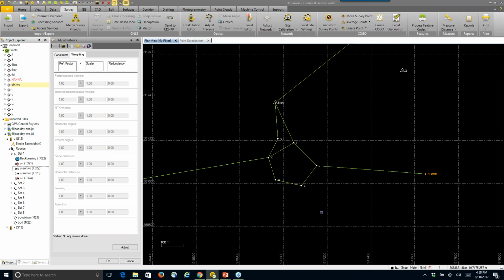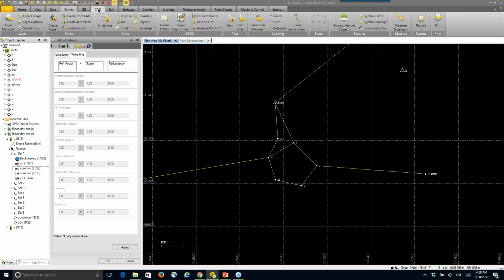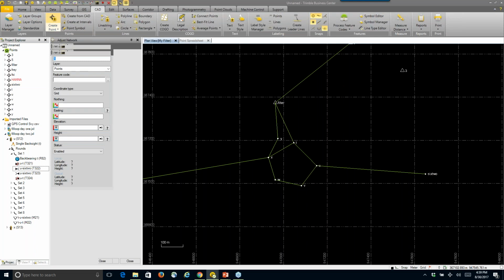That is an option. And also what you can do to test that out, if you're still a little on the fence about working with multiple data types in the same project, is if you see on the screen right now on the survey tab, right below where the survey tab entry is, there's a merge survey projects. That command will allow you to merge different data projects, different VCEs, into a single VCE. So give that a shot as well.